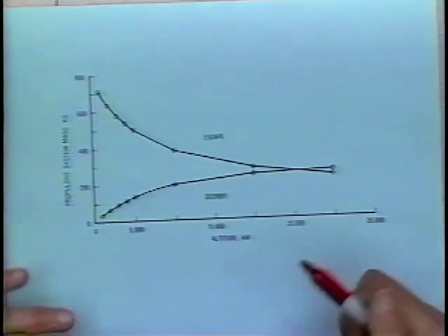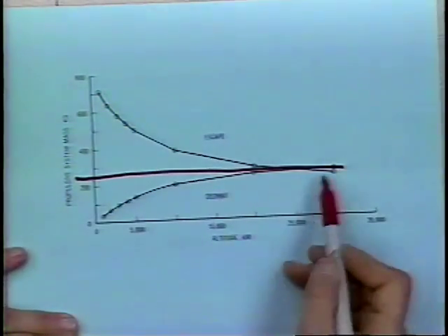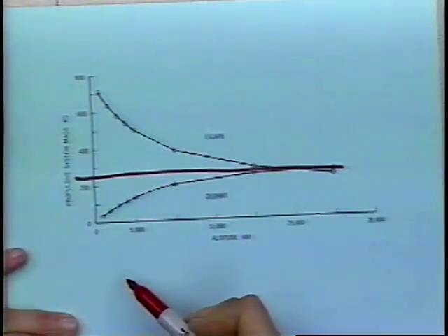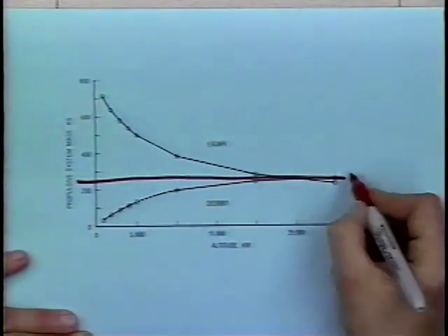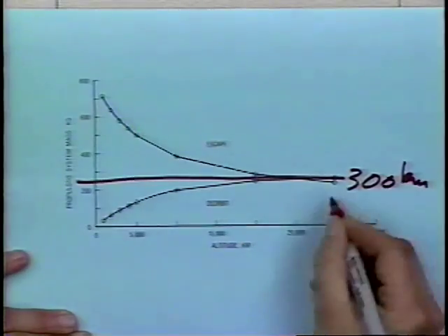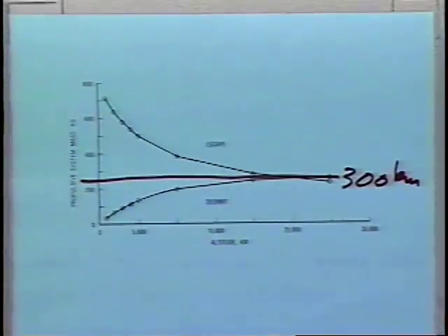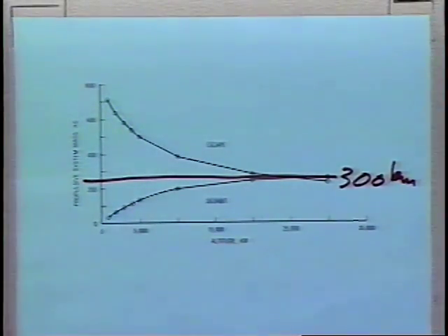Okay, well, what do we do about it? If you are below a certain altitude, it's easier to have forced deorbit and get the stuff to re-enter. If you're above a certain altitude, about 300 kilometers, it takes less energy to send something up and push it away from the Earth. So the next decade is going to see a major concern: cleaning up the Earth space environment to make it safer for spacecraft and humans to go out into space.